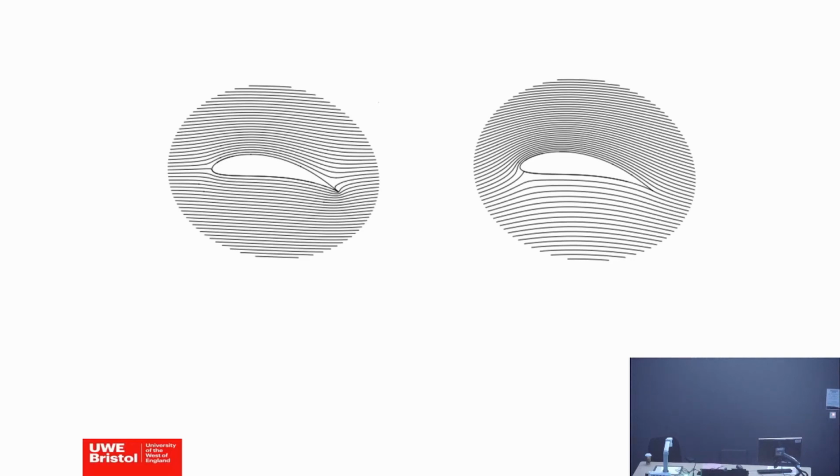Very good. Yeah, so the flow picture on the right is the correct one, because on the left we can't have flow not having a stagnation point at the trailing edge. That is basically the Kutta condition saying the flow must leave smoothly at the trailing edge. So that's the correct flow picture. That is not a correct flow picture. Okay, so this is the correct one. So try to use these ideas when looking at flow pictures next time and thinking about lift and drag. Right, thank you guys.